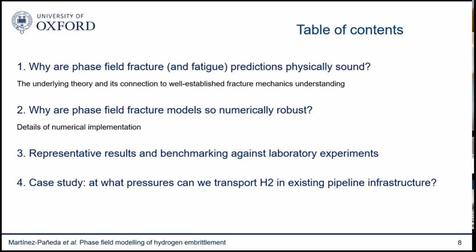And I think this is important because there are many problems, like the pipeline problem, where using computational methods can be critical, because it's very difficult for us to evaluate in a lab whether we can transport hydrogen in natural gas pipelines or not, because we know that the problem is welds. Welds have residual stresses. It's very difficult to obtain standardized samples from heat-affected zones. Welds can be of very different types. Pipelines that have been there for decades can have very different distributions of defects. You have very different types of pipelines and very different grades of steels and welds. So there are many scenarios that you need to evaluate. The scenarios are complicated: how do you introduce the residual stress in your model, in your experiments? And here's where I think a physically sound model can make a big difference.